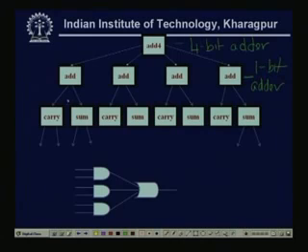And another thing you just notice, see here all the carry and sum modules are of similar structure. So, this is what we mentioned, the duplication of modules, and in digital design this is mainly the advantage, that one large system can be realized by similar modules, and it is very advantageous to fabricate the similar modules in a smaller area. That is what we call VLSI, or simply ICs also.